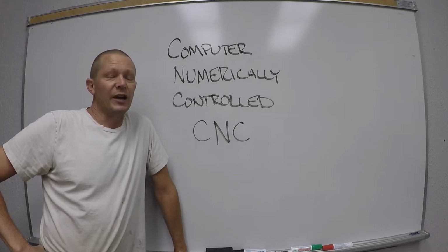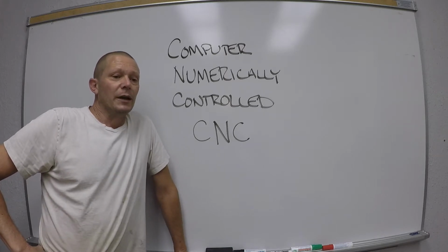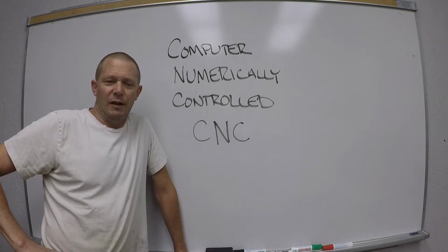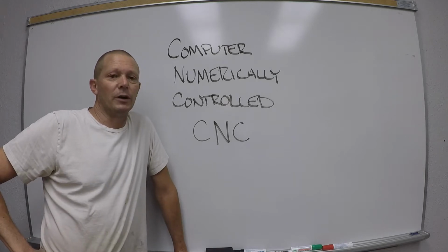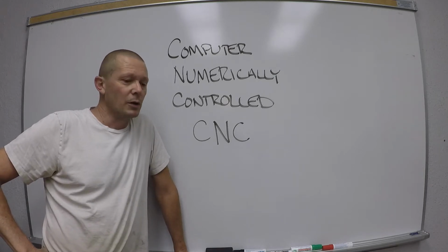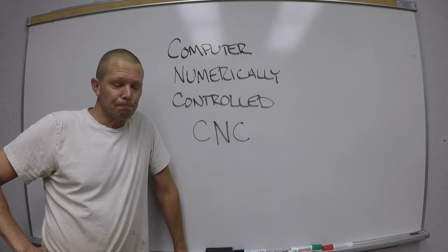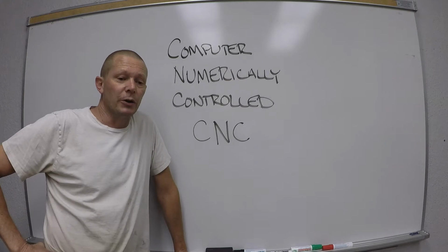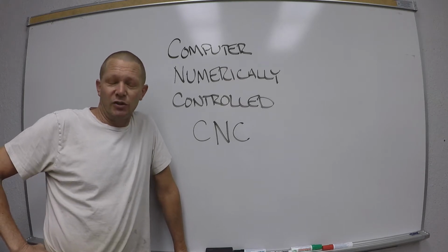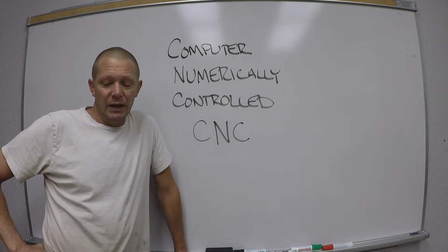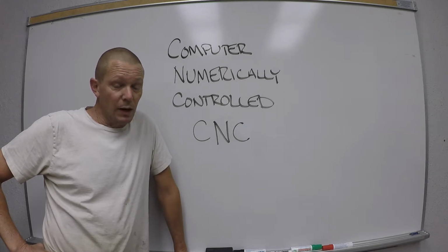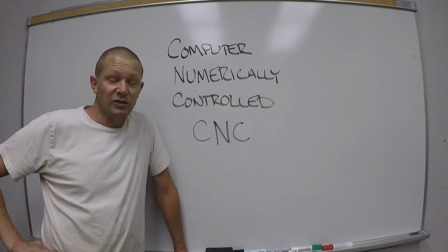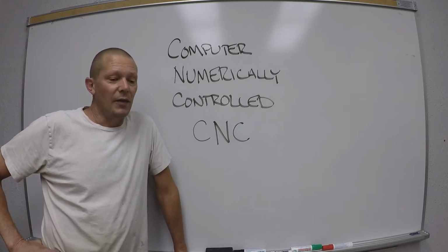So for the final exam, what I normally do is we come in for our 2 hours, or 2.5 hours, however long it is, and I bring a part in SolidWorks. I don't do SolidWorks, but I program Mastercam, and what happens is you get to see me program a very simple part. We generate the G code, which I'll talk about in a moment, and then we go out to the CNC machine and load the machine and run the machine, okay? That's a very simple part. That is usually your final.